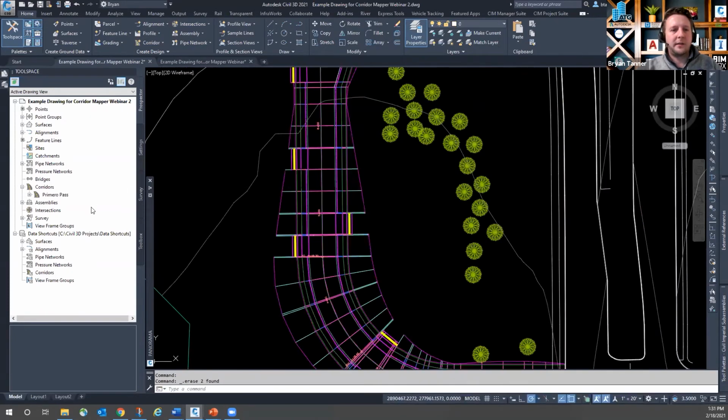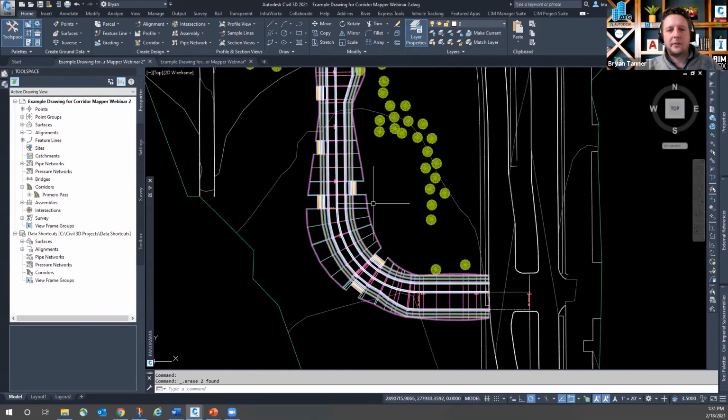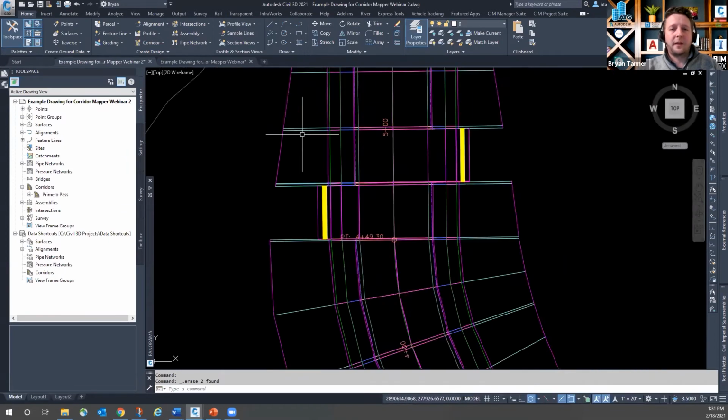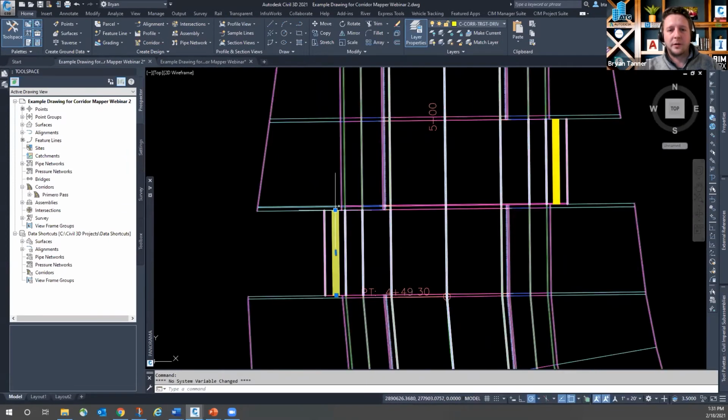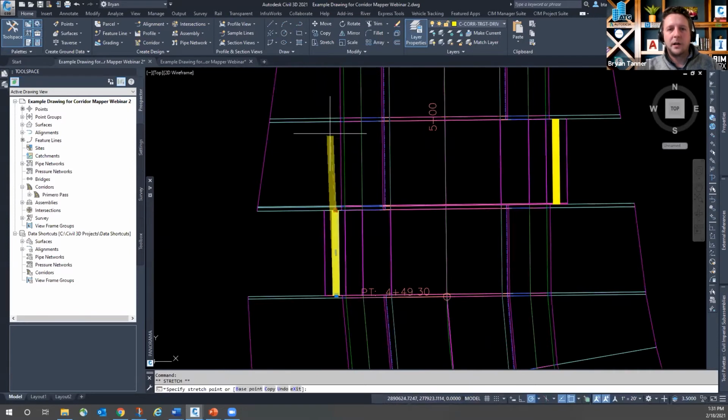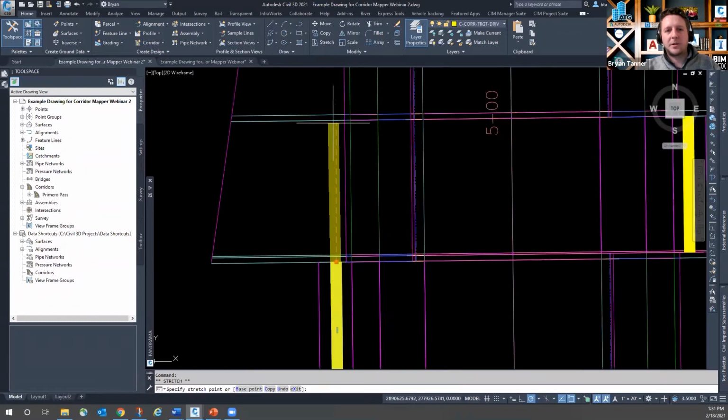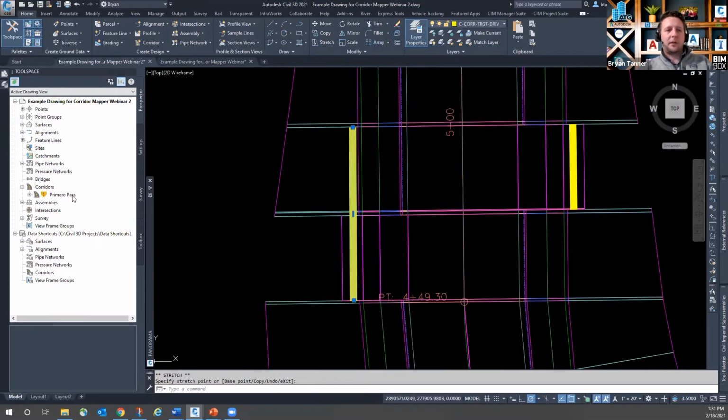Delete those polylines, our corridor updates. And just for the sake of argument really quick, for those who are joining us who've never used the tools before, Civil 3D is incredibly dynamic. If one of our drives stretches, if this represents the back of the drive or the front of the drive, depending on how you're defining it, and the width of the drive, the approach changes, well, guess what?